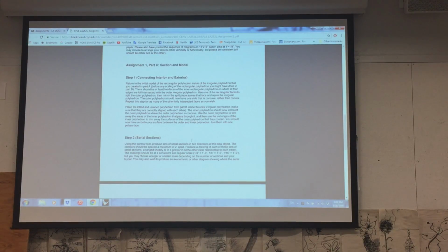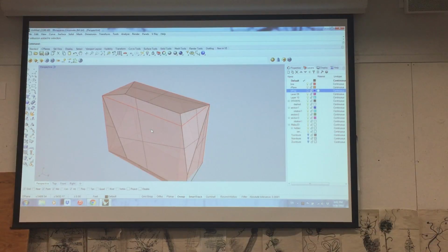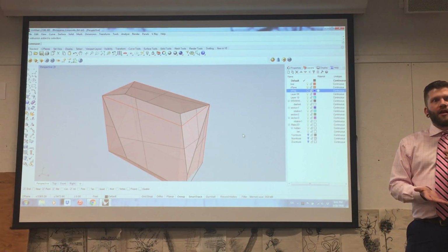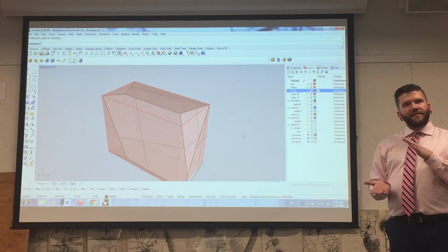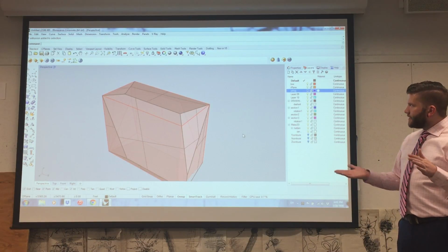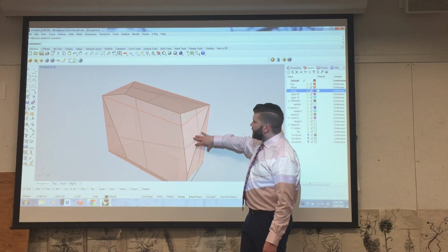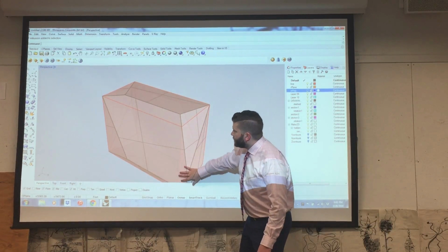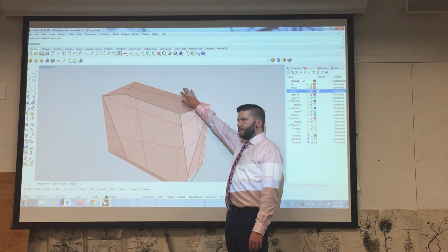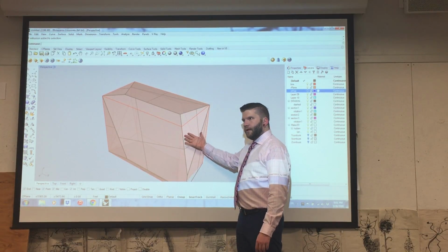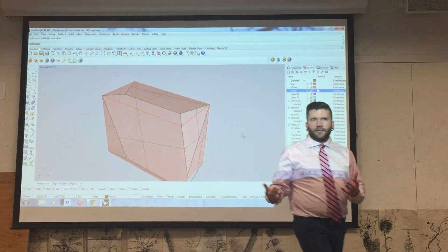So what I want to do, for my situation, is use the top plane and the bottom plane of the red cube. I want to use those surfaces to split this into two pieces. Everything basically on this side of the plane and everything on that side of the plane. After I do that split, I'm going to mirror it and then rejoin it back to its original.